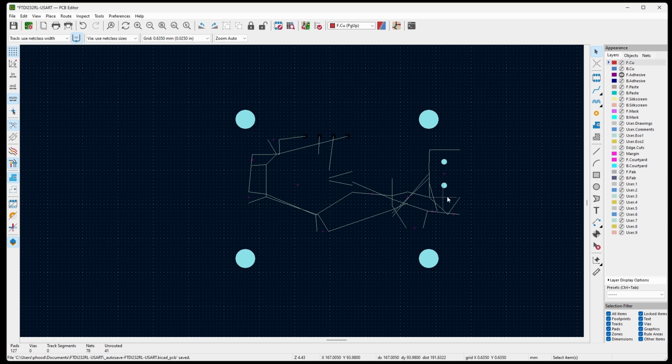Adhesive layer: the USB connector has two adhesive locations because that connector will get some abuse over time with the constant plugging in and unplugging of cables into that particular connector. So it needs some mechanical support to be able to make that connector robust.